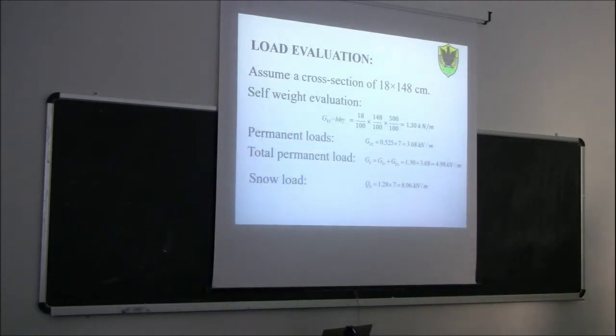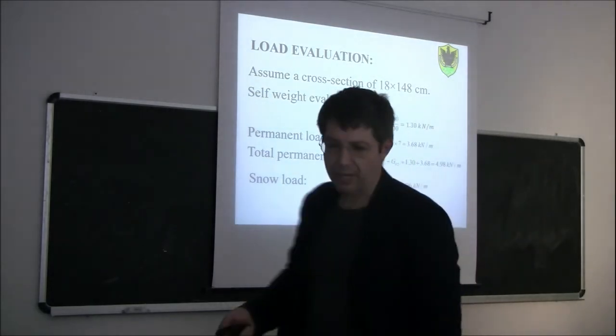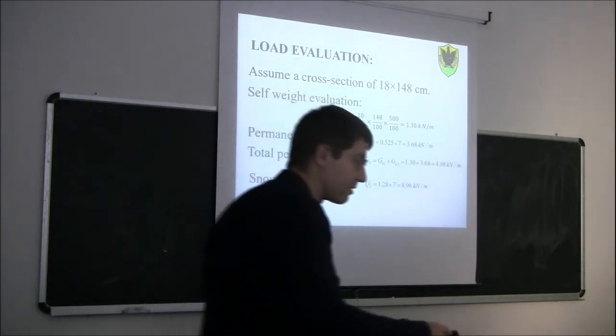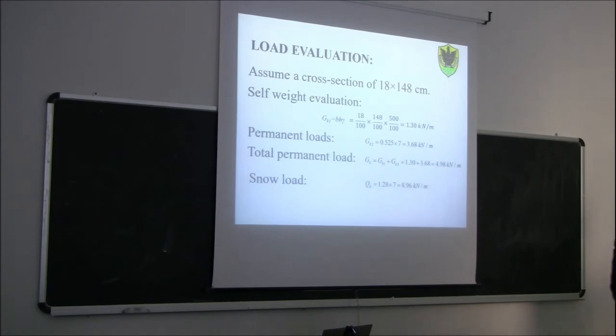So as a matter of comparison, just this. I repeat again. Here we need more or less 50% of the live load as structural weight, while for reinforced concrete, we had that 300% of the live load, or 200%, was self-weight. So the ratio is 4 to 6.